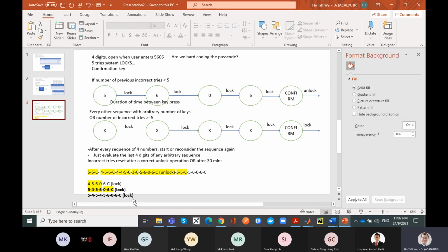You let the synthesis tool make the decision for you and you don't really know how your design works, and then something happens and it breaks, and then you say, oh, the tool is problematic, this is some black magic. No, it's because you were not thorough enough. And the key problem here is you need to consider all the possible sequences. This is what we mean by specification.